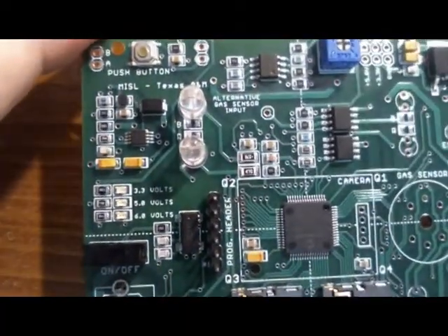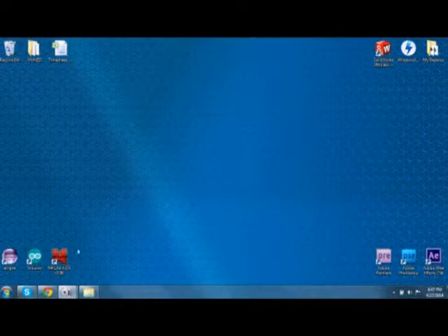Now that we're done installing the red and the blue LED, we can go ahead and begin programming them. In order to demonstrate the usage of the LEDs on the NESI board, we're going to make a simple program which will turn the red LED on, then flash between the two, so red then blue, and so forth.